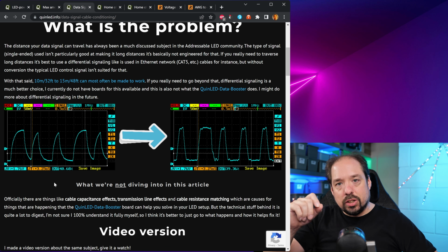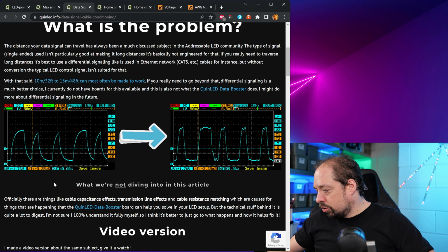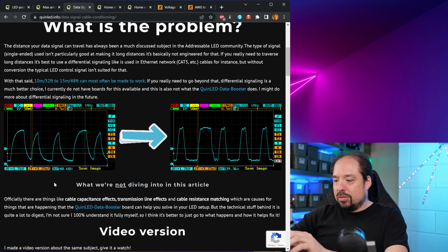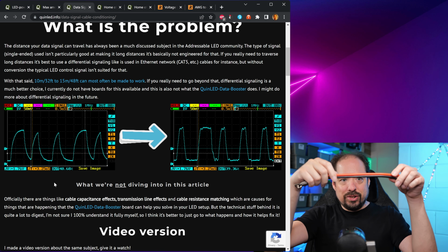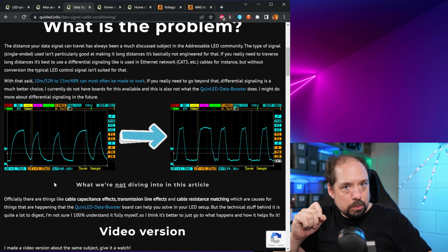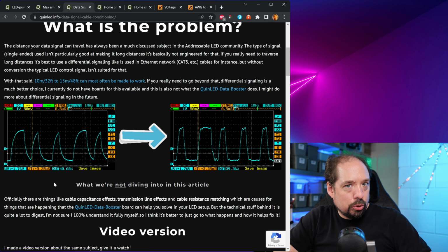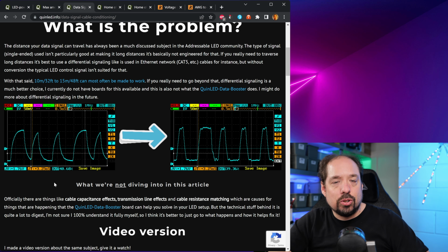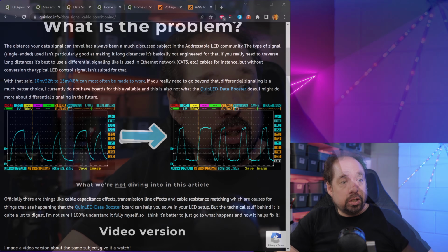But if you have a long data wire, and you run ground next to that data wire, so a 2-wire cable that's basically attached to each other, a normal cable like this, or I'll show you this variant, then flip that channel with the dip switch on the Dig board to 33R mode, which is optimized for having ground next to your data wire. That will work a whole lot better. Okay, I think that does it.